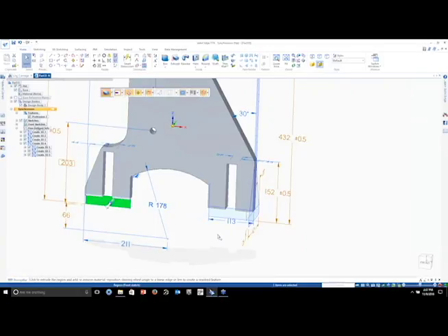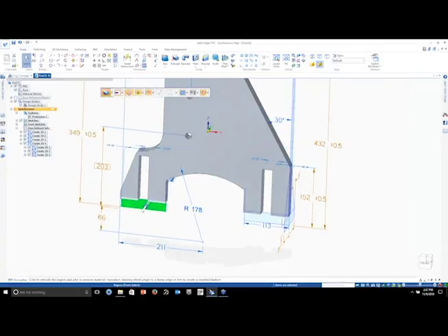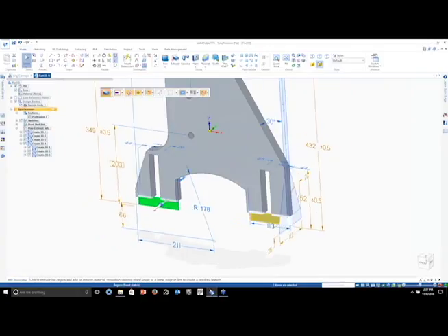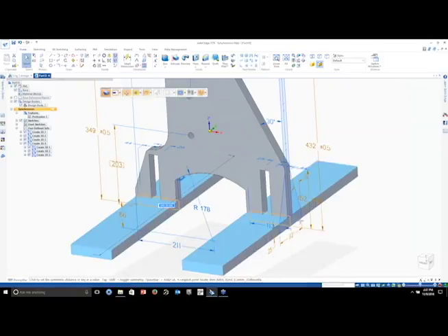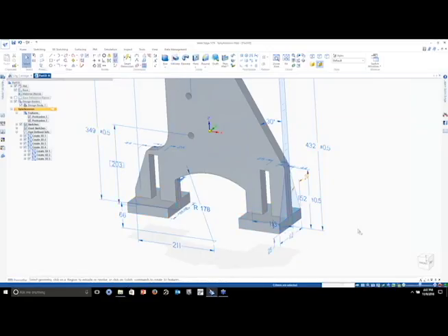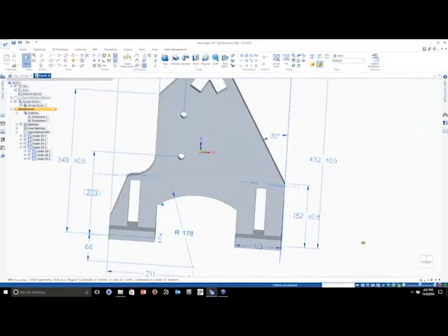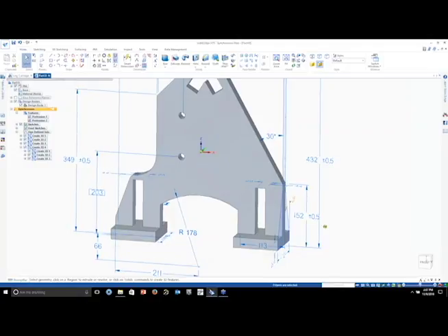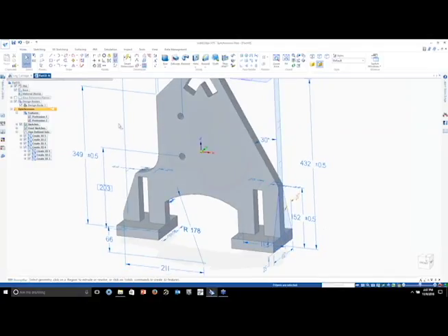Well, there's a couple different ways to get them, but remember earlier when I said you can restore sketches? Well, I can come back and restore that sketch, and now it's restored, so now I have a region to grab. So I can grab that again, hitting Shift, grab that region, and start extruding it out, and go to the edge of that. And now let's go ahead, and since we could either cut that away again, or we could use the steering wheel.